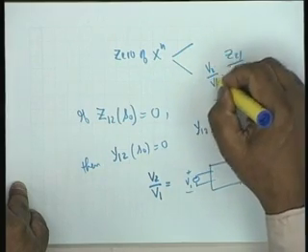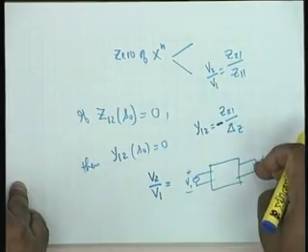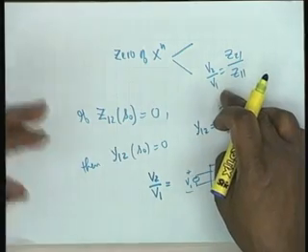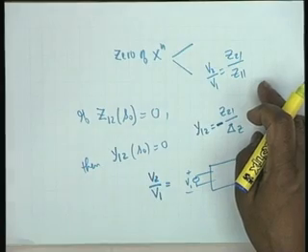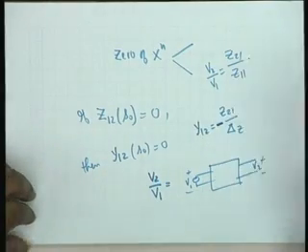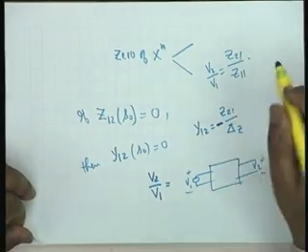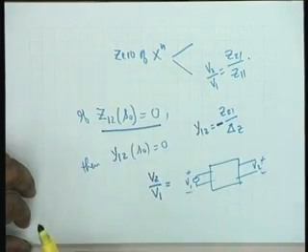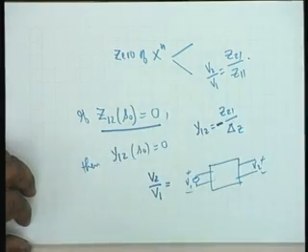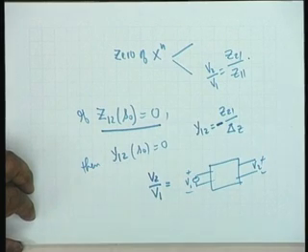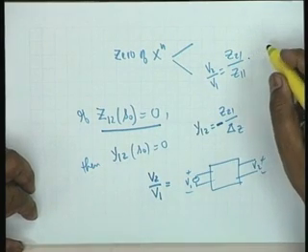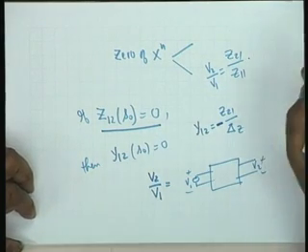You write the voltage equations and put I2 equal to 0. So you get V1 equal to I1 Z11 and V2 equal to I1 Z21. The ratio is simply Z21 by Z11. Therefore, if Z12 has a 0, obviously the voltage transfer function shall also have a 0. Not always. There is a qualification required, which should be obvious. That's right. Z11 should not have a 0 there.